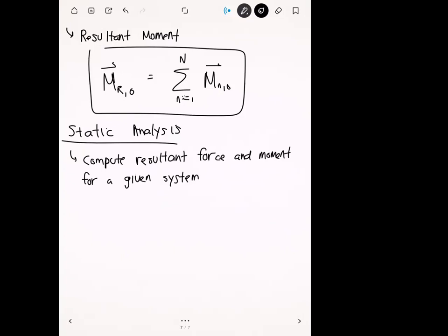And so this system is going to be comprised of lots of different forces, okay? And so you're going to have to draw a free body diagram. Drawing a free body diagram will help you a lot because it'll help summarize all the different forces that are there, okay? And then what you're going to do is set all the forces equal to 0.